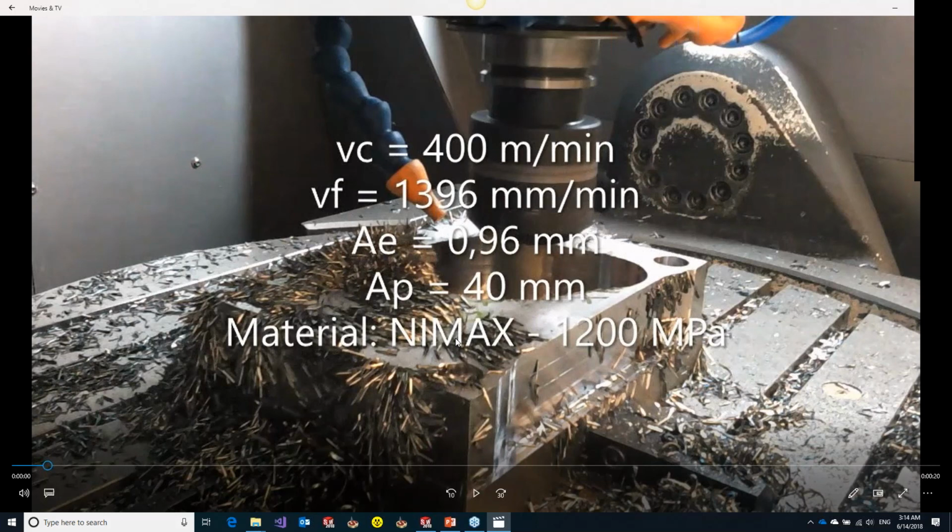It's kind of the opposite. If you get specific insert cutters that are meant to work with iMachining, you can get much better performance using an iMachining style toolpath at a much lower cost than traditional insert cutters, because now we manage the engagement angle, the inserts are going to last longer, you can cut faster, et cetera. Once again, you're going to need a big machine to do this. You're not going to take a small machine and throw an 80 millimeter cutter at steel and expect it to work.